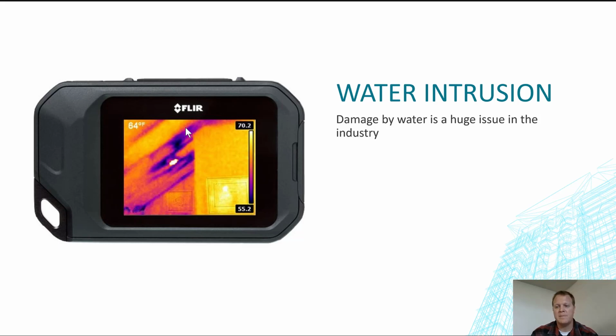Water intrusion is huge. So on a project, this has been ingrained in me over the last like 5 years, dealing with some of the insurance folks and how big of claims can happen. But really you've got to be paying attention to: Is your piping really tested? Do you know where your isolation valves are on a project? Are you shutting water off during the end of the day? Things like that limit your risk associated with water from piping.